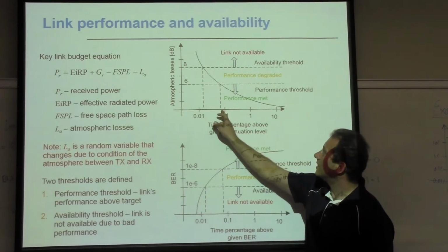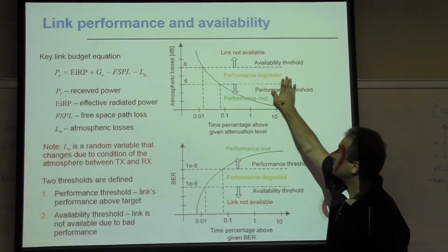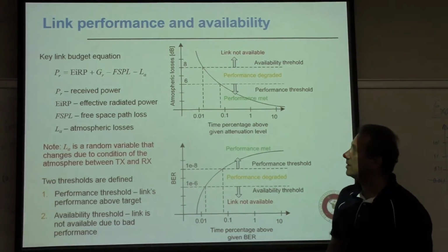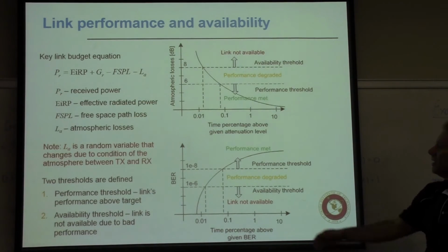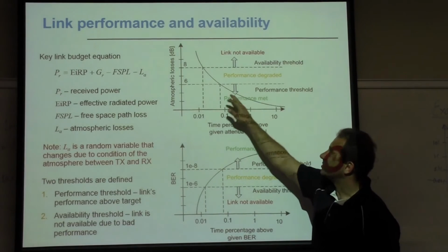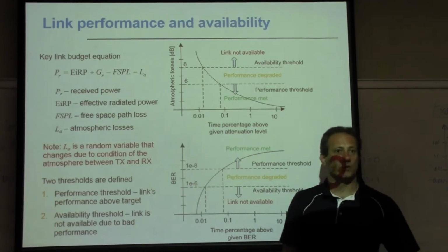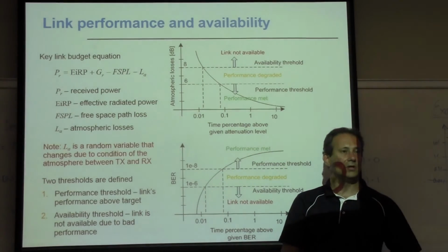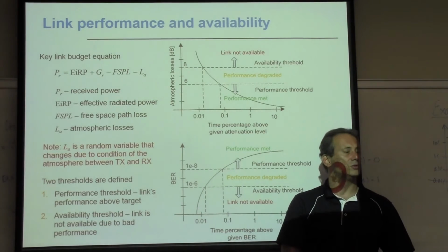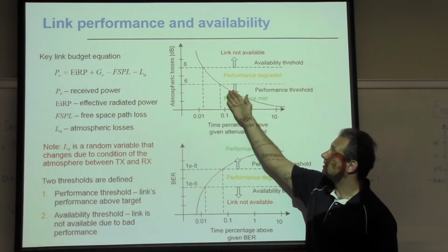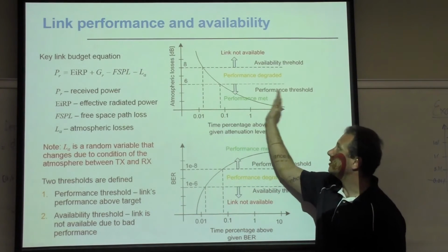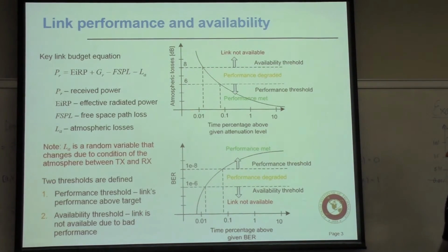He defines a gray area too, which is performance degradation, where you have a link, but let's say it communicates at a lower capability. And then here, the link was designed with a margin of 6 dB. So that means if anything introduces losses that are smaller than 6 dB, the link will overcome that. There will be sufficient power there, and the performance will stay degraded here.